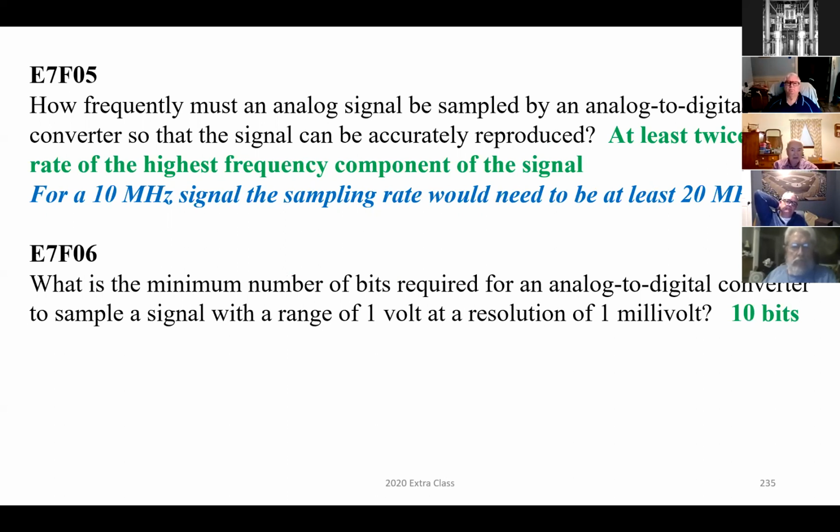And if you remember when compact audio discs came out in the early 80s, the audio for the compact disc is sampled at 44.1 kilohertz. And if you use the accepted range of human hearing, which is 20 hertz to 20 kilohertz, by sampling at 44.1 kilohertz, that's a bit over twice the highest frequency of that signal.